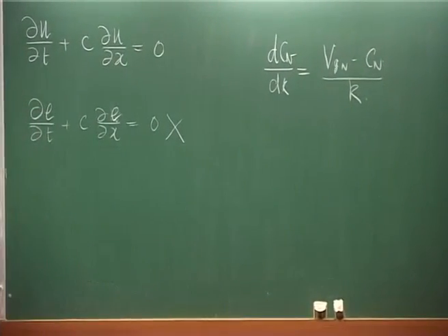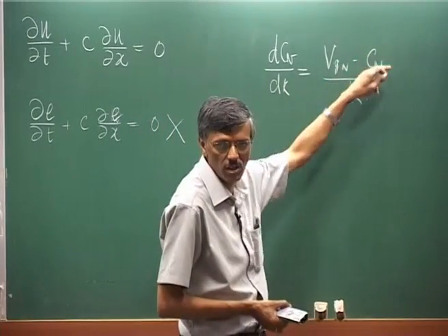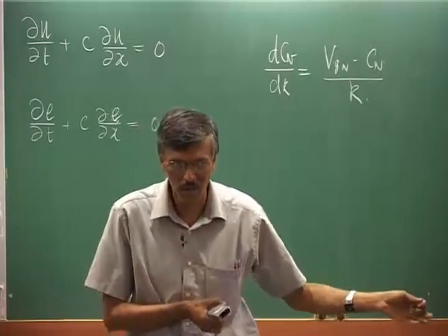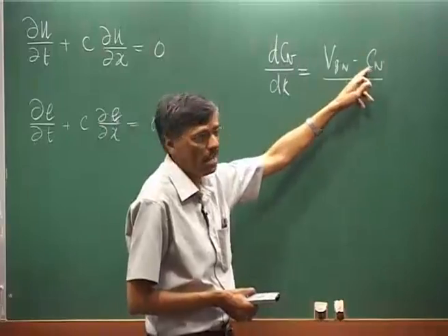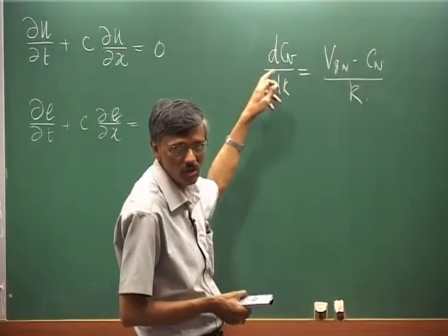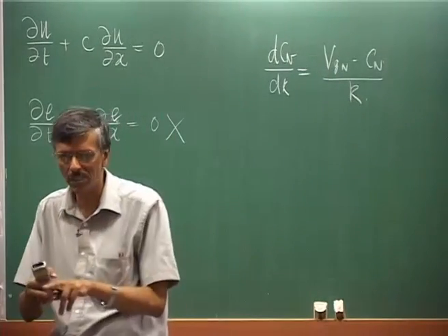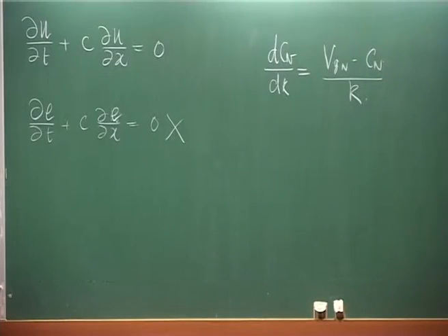If you are looking at the original physical problem, both of them are the same, Vg equal to C, so you do not have it. This term is identically 0 for the exact solution, because Vg equals C, it is a non-dispersive system. But in this case, we found Cn is a function of k, that is why this is non-zero, and that is caused by the departure of the numerical group velocity from the numerical phase speed, scaled by the wave number k itself.